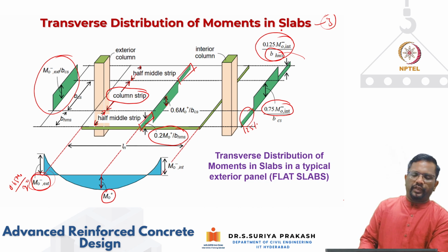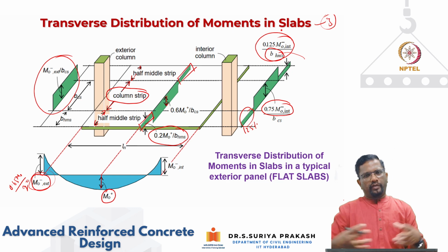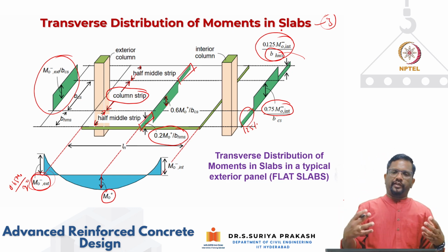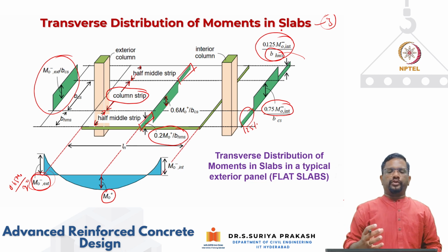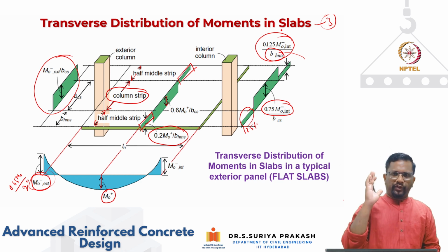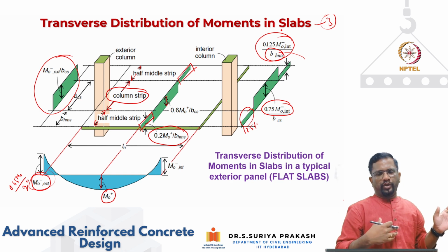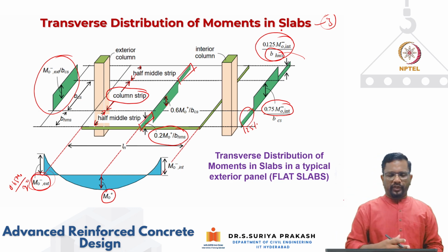So in this way, depending upon wherever there are stiff regions which are along the column strip, the direct design method is saying that you put 60% in column strip. For example, mid span of exterior span, whatever the moment longitudinally we got, 60% of it should go to column strip, only 20% on the left side and 20% on the right side.